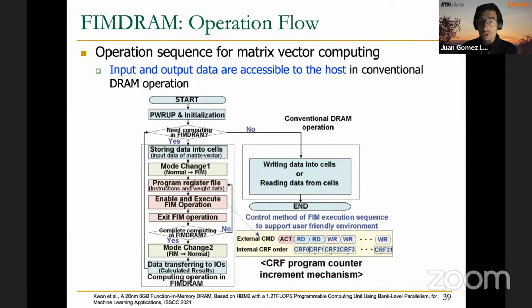And from that point of view, it's also similar to the way that kernels are executed on UPMEM DPUs, because as you may remember, we talked about these 2 lectures ago, the execution of the DPU kernels happens between accesses of the host CPU to the PIM enabled memory, to the MRAM bank.